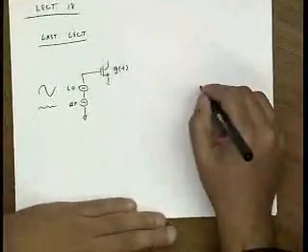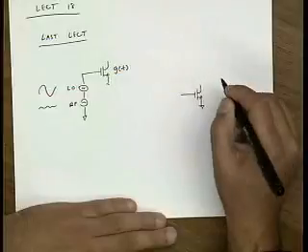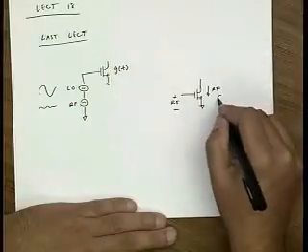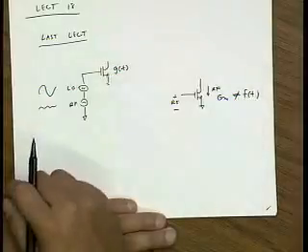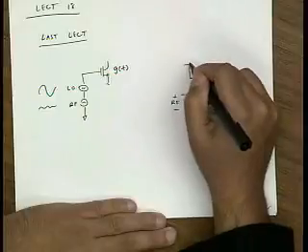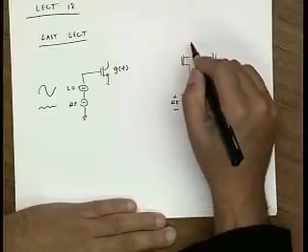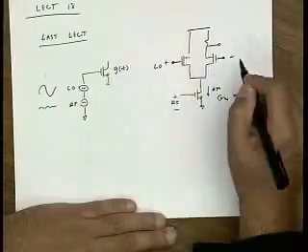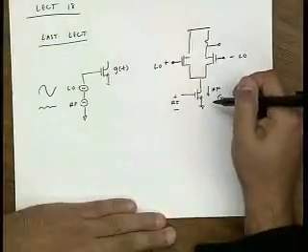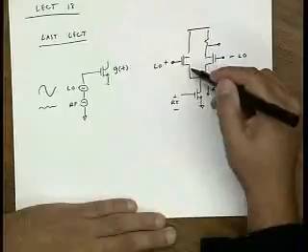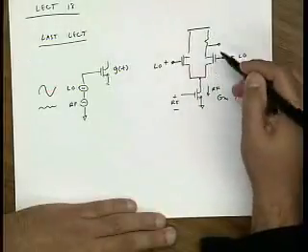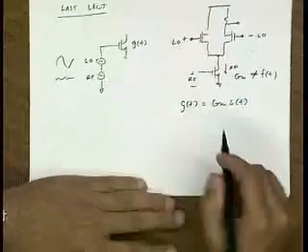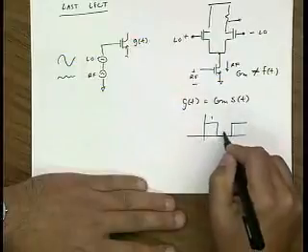But then we also talked about another kind of mixer where we have a transconductor that essentially just takes an RF voltage and converts it into an RF current. And so this transconductance is constant. It's not a function of time. And then we create time variation using switches. So in this case, we have a current switching pair. So we could take our output here and drive this differentially with our LO. And basically on the positive LO cycle, we take our RF current, we dump it to supply. On the negative LO cycle, we take our current and we dump it to our load. And so effectively, the total transconductance is a constant times some switching function. And in this case, ideally, the switching function will be 1, 0, 1, 0.